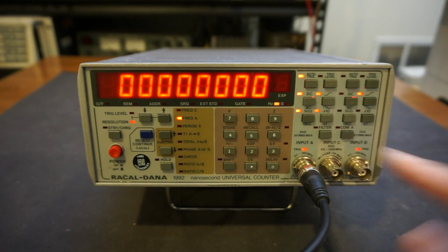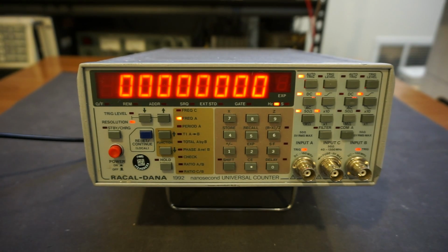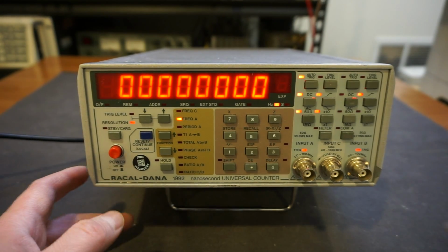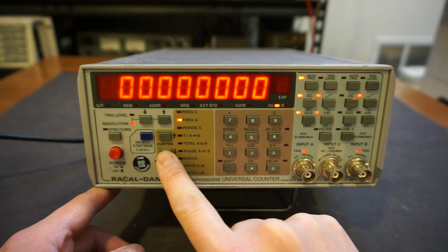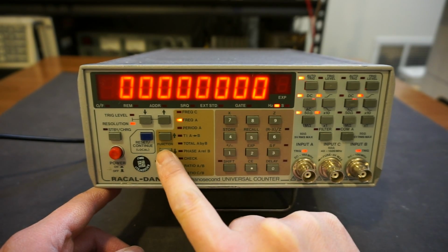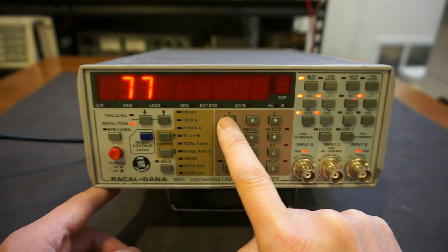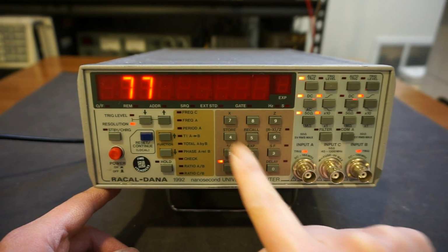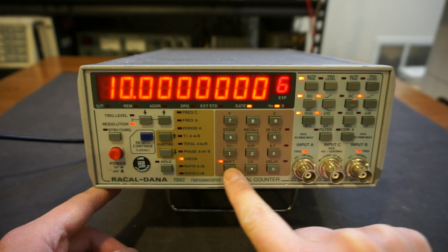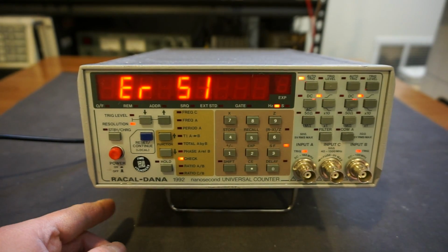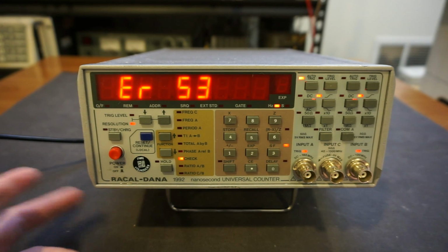it doesn't seem to work. And now if I run some diagnostics according to the service manual, diagnostic routine 77 and 78 checks channel A and channel B, and you will see that we're getting some error codes. So let me just demonstrate that. Let me get this first into check mode. So let's go down to check, and if I remember this correctly, 77, shift, store, SF, shift, SF. Here we go. So that's the first error code, 51, and then gives 53.